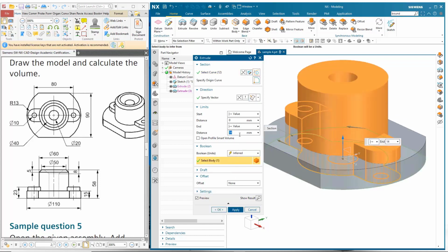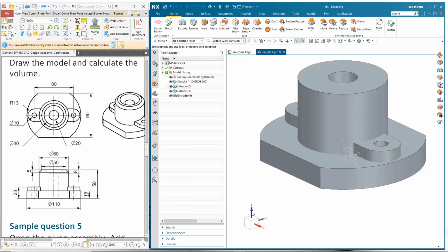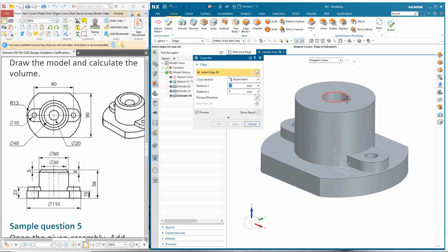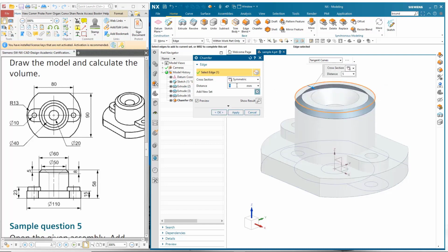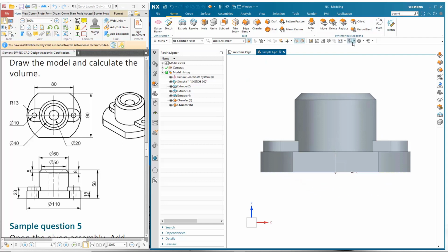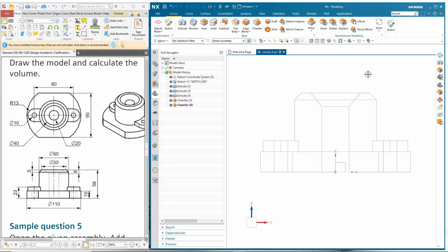That means they will unite or subtract, as I understand. The last one, I want to go with a 15. So quickly, I have the proper geometry. I want to create some chamfers. Based on the value, I know that I divide that by half, so I have a 10 and 8, and then the outside chamfer. But then a lot of times I just want to quickly check my work.